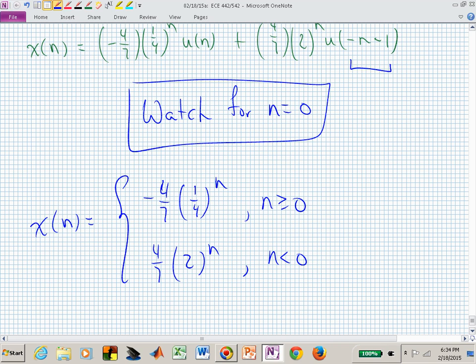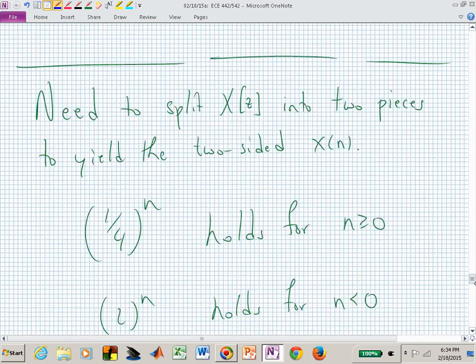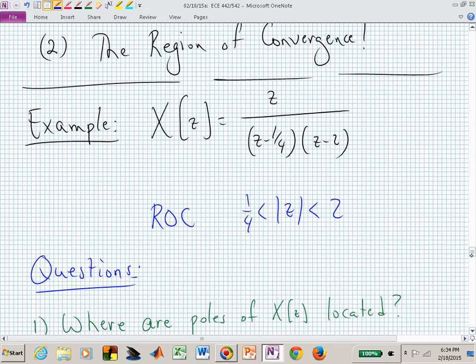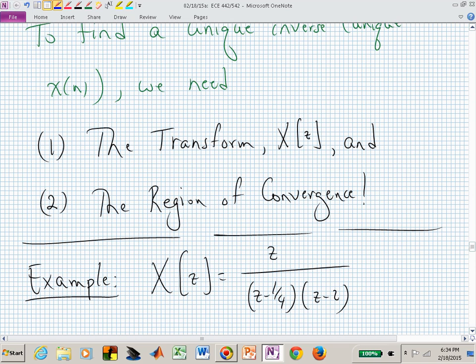We have the capital X of Z that we started with. There's capital X of Z. Don't think of that region of convergence. I've now changed the region of convergence to be interior to 1/4. Is the signal waveform in the time domain one-sided or two-sided? Show of fingers at the count of 3. 1, 2, 3. It's 1, isn't it? We have something that's not annular, so that tells us 1.